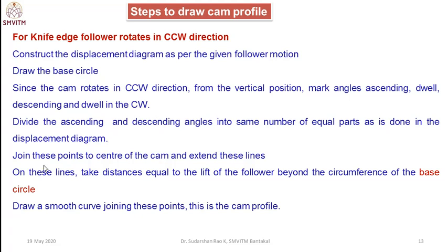Join these points to the center of the cam and extend these lines. On these lines, take distances equal to the lift of the follower beyond the circumference of the base circle. Then draw a smooth curve joining these points. This is the required cam profile. Okay. Thank you.